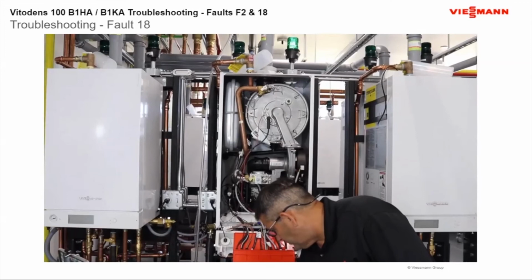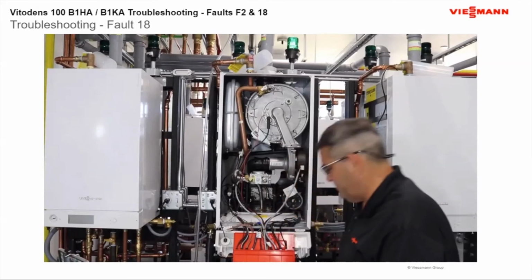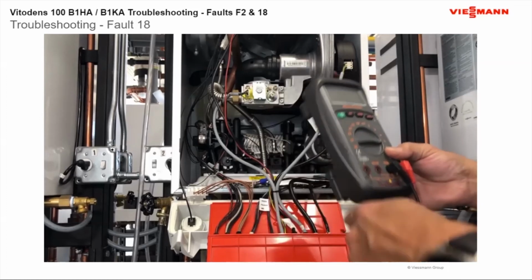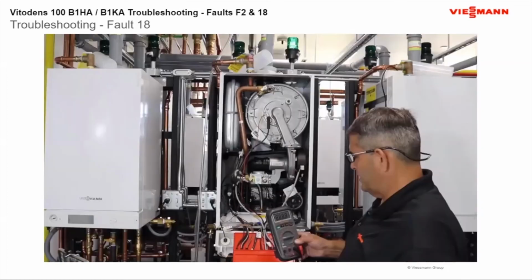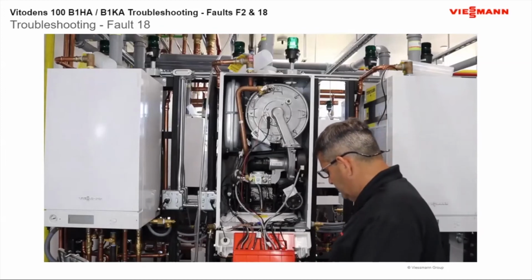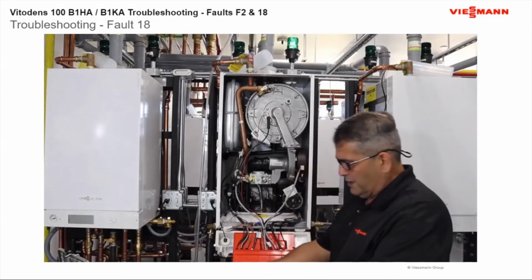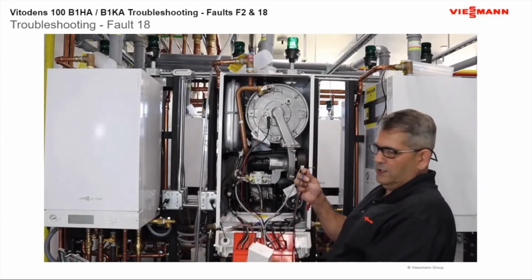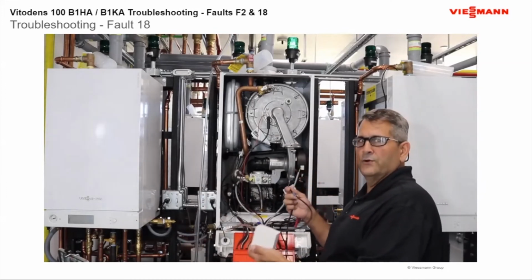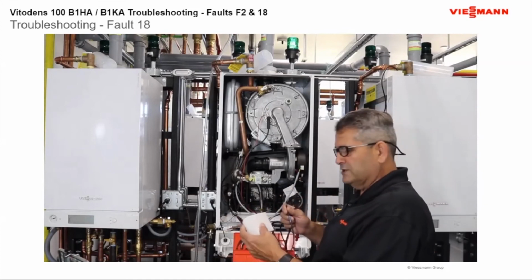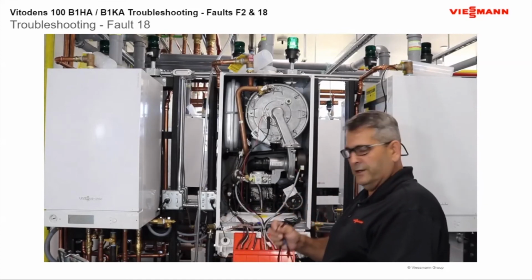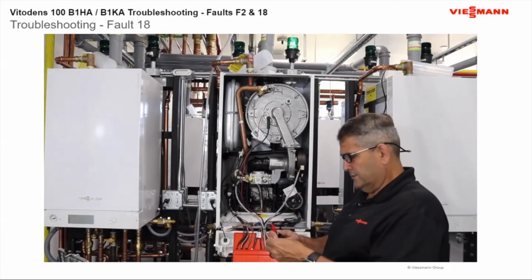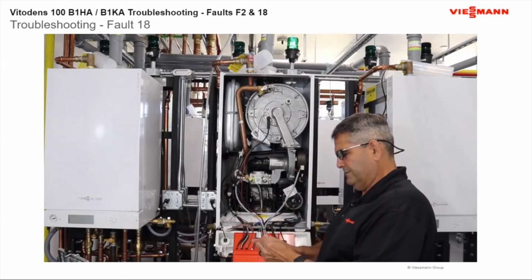So on this one here, we're going to take our meter and put it on ohms. Once we do that, we'll turn on our power and we're going to just go across our wires going out to our outdoor sensor. Remember, this wire going outdoors to the northwest side of your building could be 125 feet long. And remember, that's where we want our outdoor sensor, on the coldest part of our building, not under a dryer vent or anything like that, which we have gotten before.